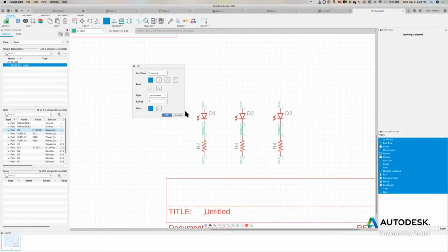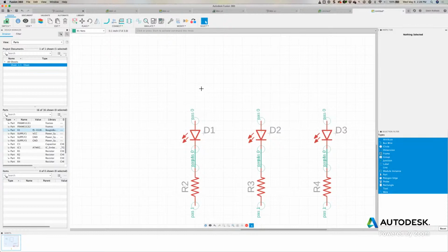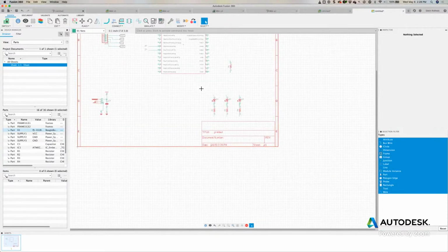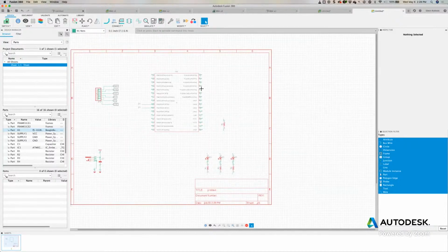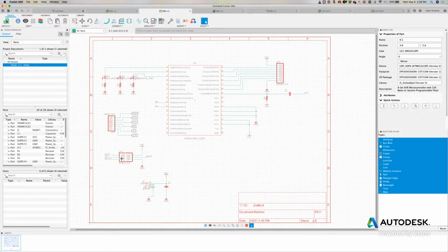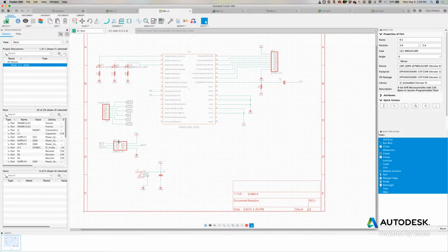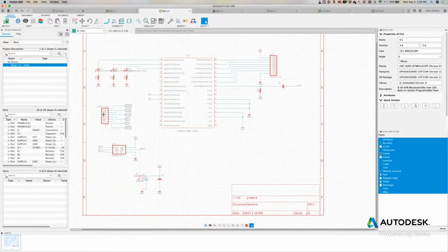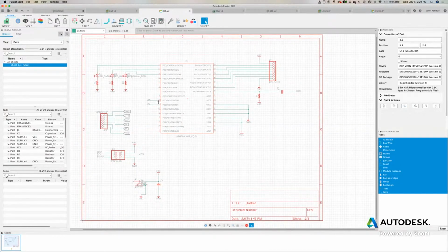and some of these connections are actually going to be coming over from our ATmega component. I don't want to continue here because if not, the whole presentation would go on this. So I do have the schematic fairly completed already, so let's go ahead and line that up. This is what our schematic will actually look like. As you can see, this is my programming header here, just using a regular 6-pin, 2x3 connector for my programmer header. And here is the pin header, as well as my LEDs.